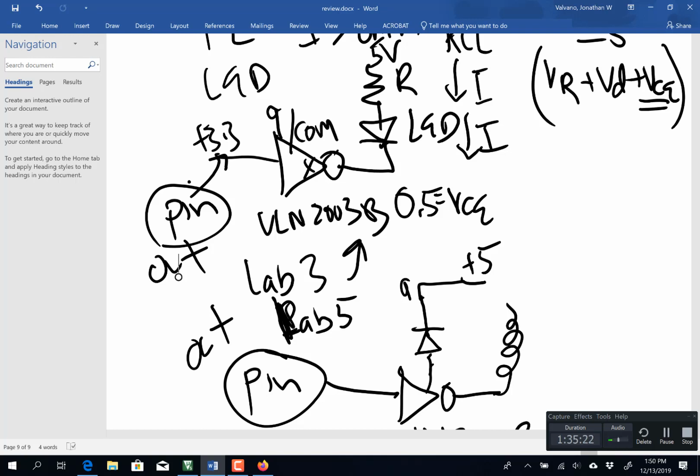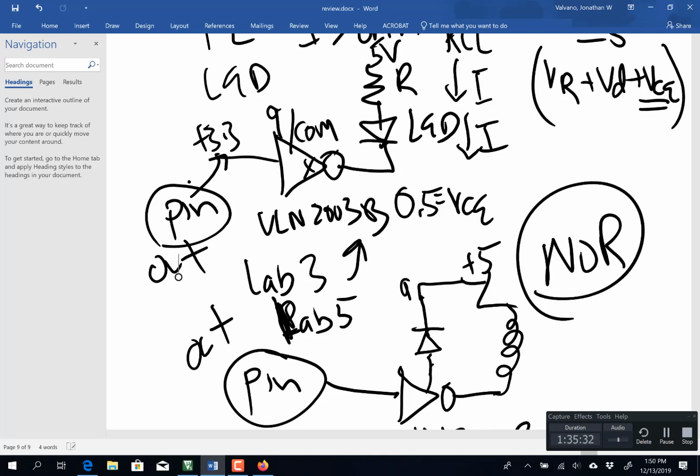I mean, maybe you've had switches, but for the stepper motor, did you have any resistors? No. So the thing that's different is there's no resistor here. You put what voltage is across the coil when it's on? What's this voltage? Right, if this is 0.5, just like it was up there, this gets 4.5 volts.